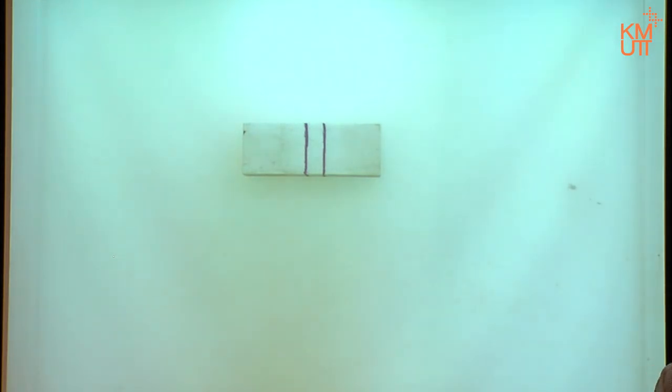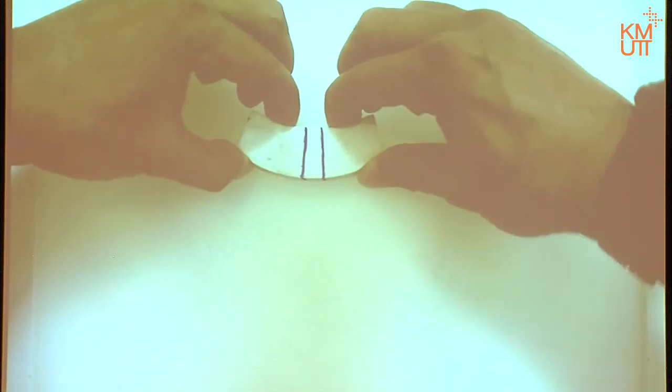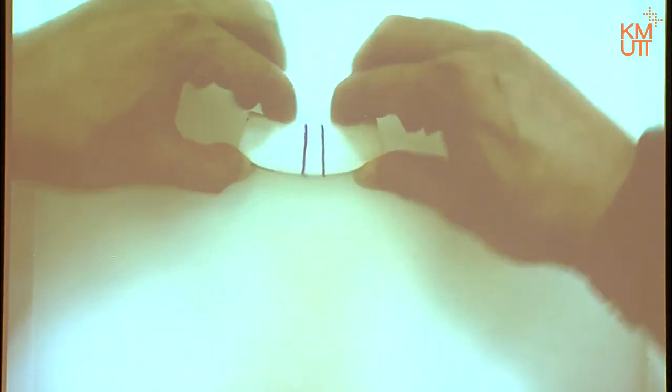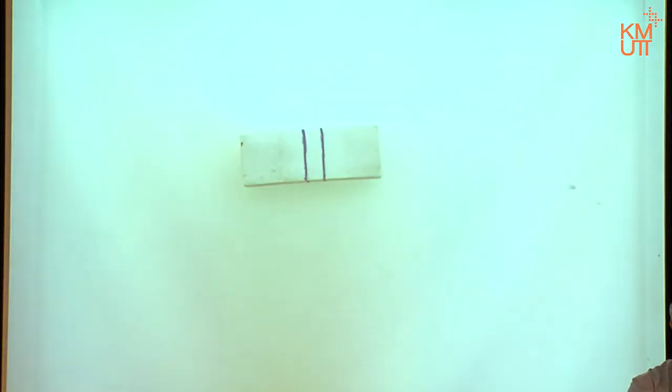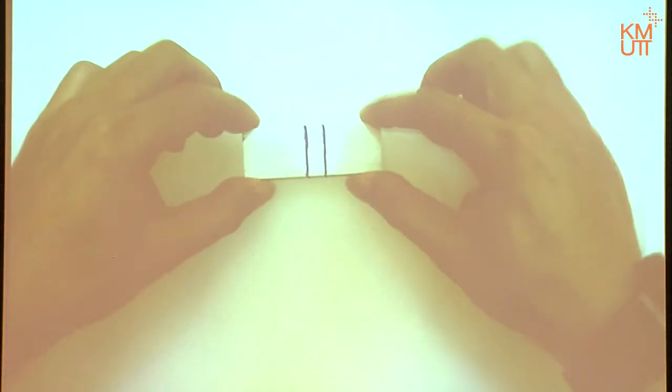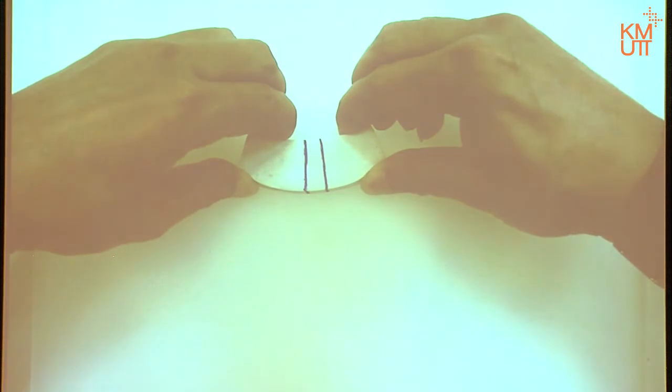Okay? Then the last one is the moment. The moment, what it does is that it bends the structure. Okay? It bends the structure. Okay? If you look, the cross section doesn't move. In fact, the cross section rotates that way and that way. Okay, look again. There, and then that one. Okay, so that's the definition and direction that we're looking at.